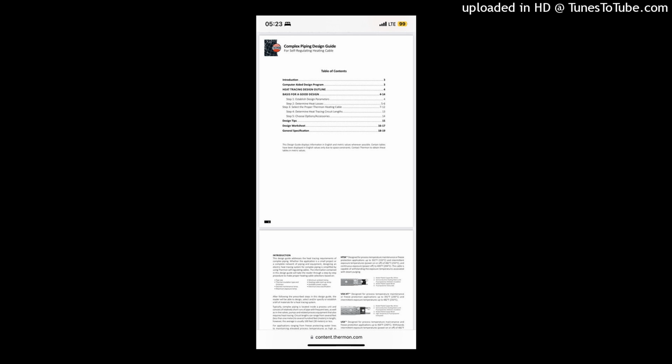Generally, this number is obtained from weather data compiled for an area and is based on recorded historical data. There are times, however, when the minimum ambient will not be the outside air temperature. Examples include pipes and equipment located underground or inside buildings.